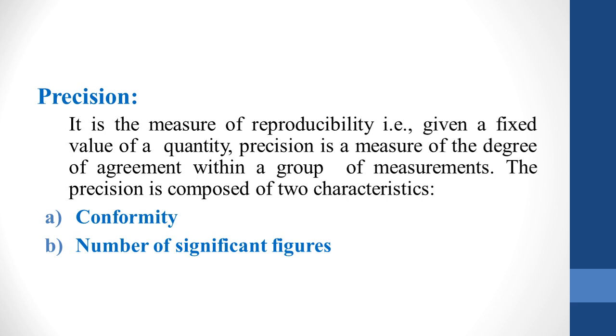For example, we have an ammeter which possesses a high degree of precision by virtue of its clarity, legible, finely divided, distinct scale and neat edge of pointer with mirror arrangement to remove parallax. Let us say that its readings can be taken to 1 by 100 of an ampere. At the same time, its zero adjustment is wrong.